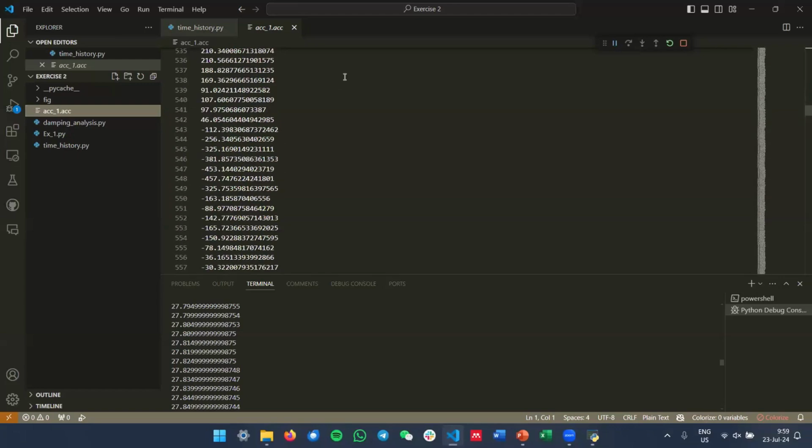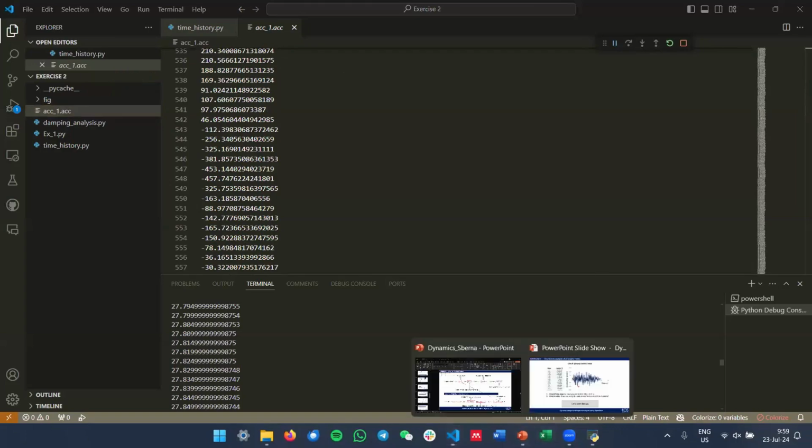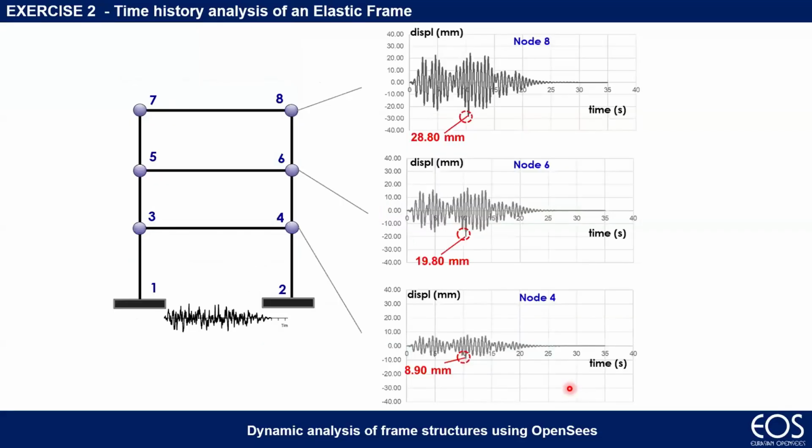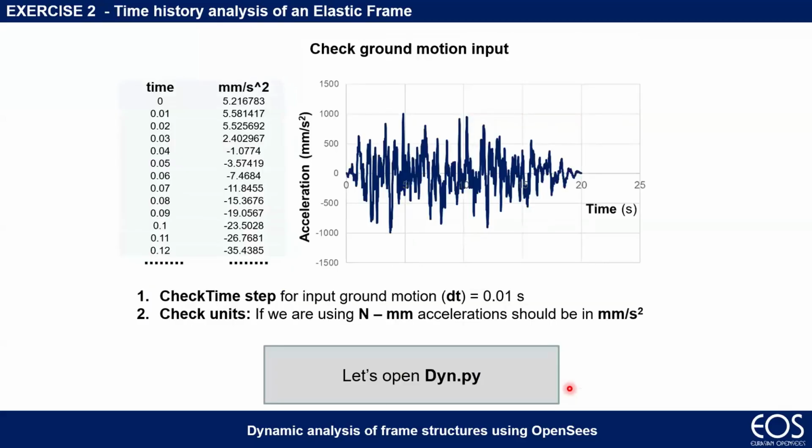You have to check. This is a strong suggestion for you: check the ground motion that you have. It should be just one list of accelerations coherent with the unit system of your structure. Otherwise, it's not working. Okay. Other questions?